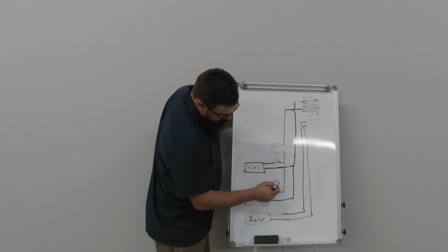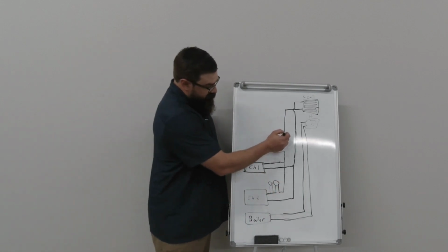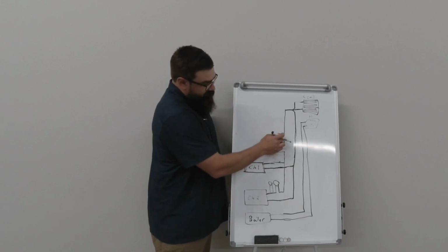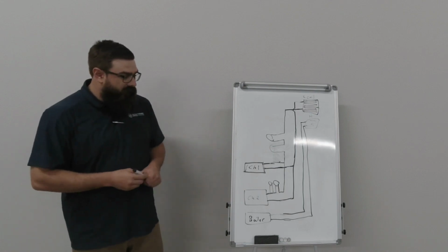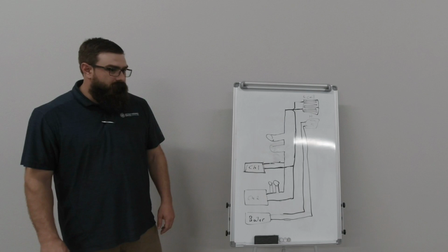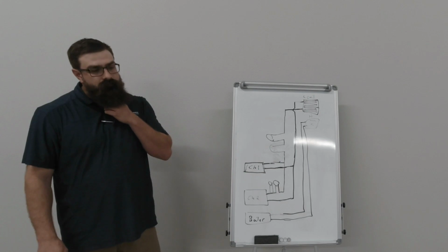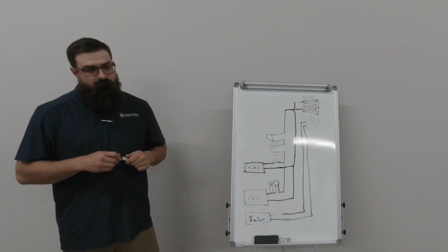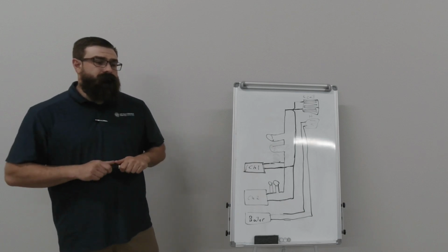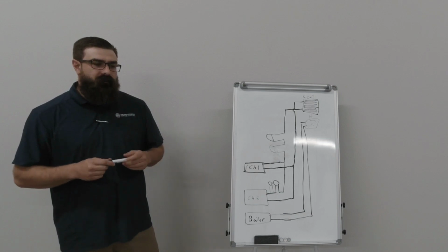both that can pump through the chiller, and it can flip-flop those pumps instead of like this where I flip-flop through the pumps, or the control system, however you want, or the chillers themselves, whatever it may be. And I think the cost of install probably plays a factor of that. Because of the common header system, it does require a little more material. There's a lot more programming, there's a lot more that goes into those types of systems versus a dedicated. Dedicated is more simple. 800 Brazos is an example of dedicated pumps with secondary versus Burleson, which is all